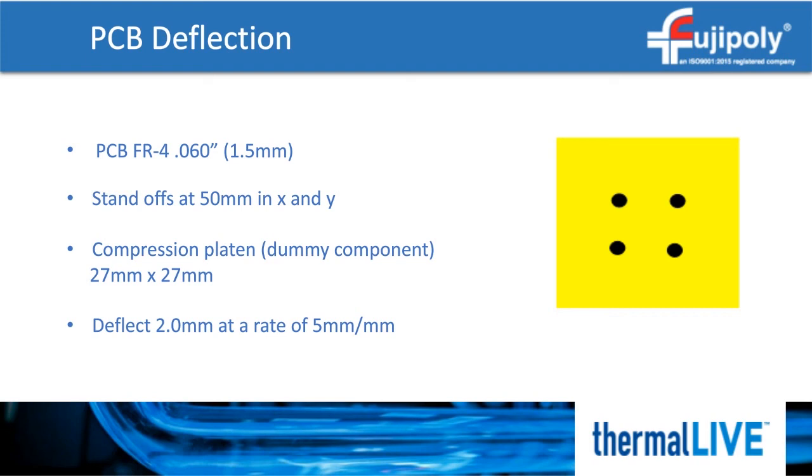Boards are packed with surface mount components and traces that are designed to maintain signal integrity at higher frequencies. Laying out a PCB is a time-consuming process. Sometimes it's not as easy as moving a BGA over 10 millimeters to accommodate a through hole, or rerouting a trace around to allow for a post to be inserted. This is why it's really important to identify components that will require thermal gap fillers and ensure they can support the compression of the pad.